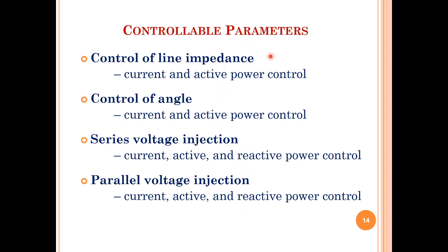Remember, Z, delta, voltage injection in series and parallel. But for impedance and angle, we cannot have any impact on reactive power. We can have an impact only on current and active power. Whereas with voltage injection, we can have an impact on all the parameters: current, active and reactive power control.